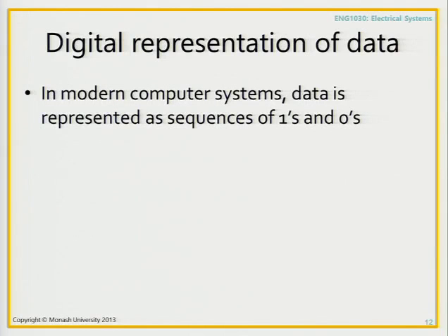If I had 3 levels, so if I had 1 level here, 1 level here, 1 level here, and I had that amount of noise, well, then it starts getting a bit fuzzy. Like, how do I know that something here was actually the middle level or was it the bottom level? Okay, so the more levels you have, the more tricky it gets. So that's why 2 levels, or 1s and 0s, tends to be the best, gives you the best differentiation between 2 values.